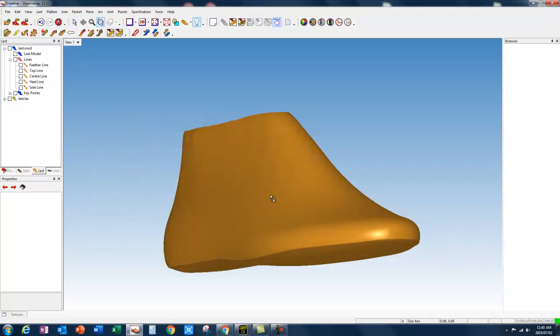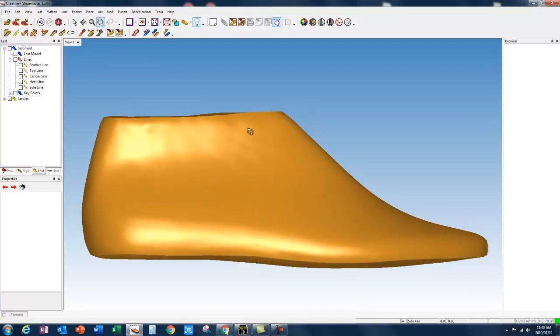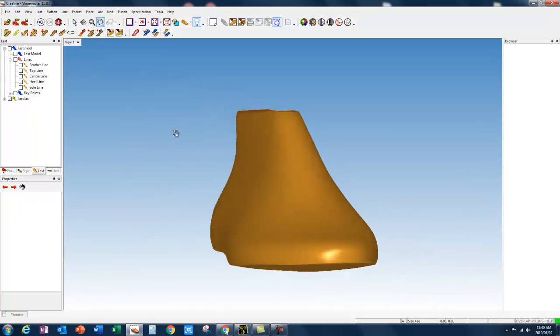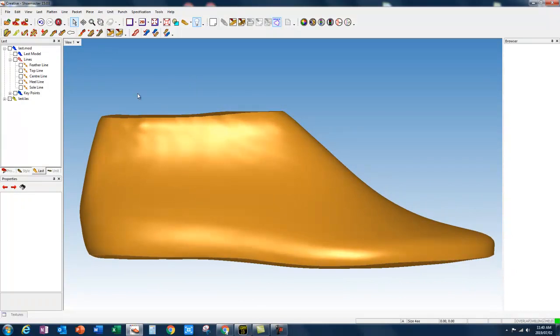Okay. The next thing I want to look at here is the roll. So this is going to be last, settings, pitch and roll, roll, adjust the roll. Oopsie. So I want this to be 30 millimeters away from the seat space, and there it must be 0. So 30 space 0, and you'll watch what happens on the screen now. See how it turns. That's the pitch and the roll. Okay. And now we're ready to flatten this.